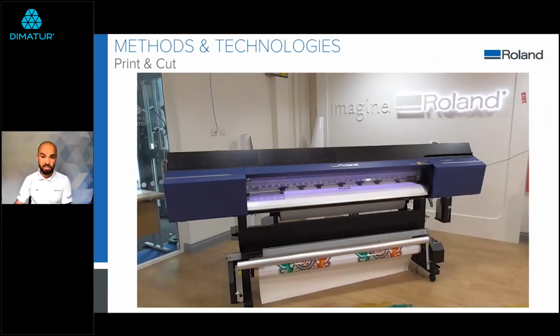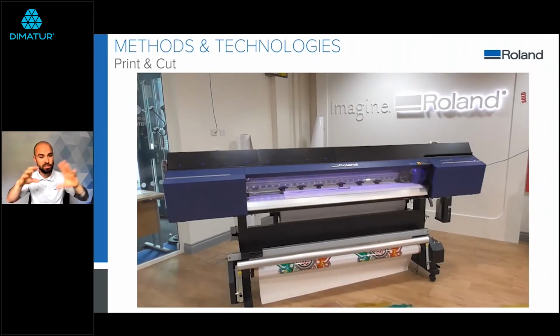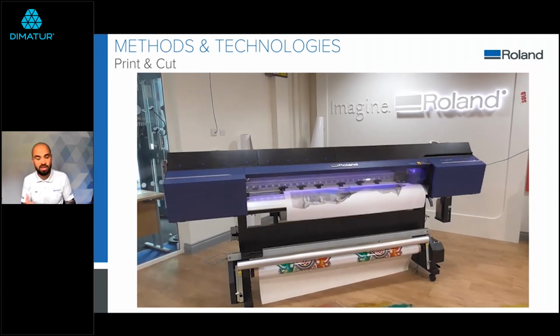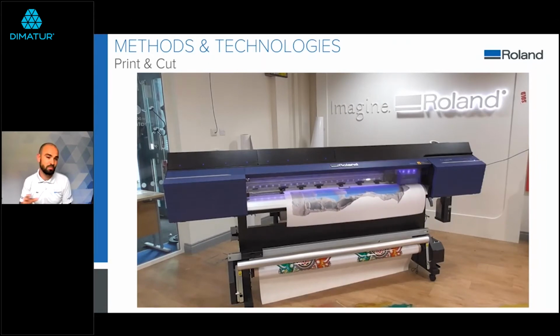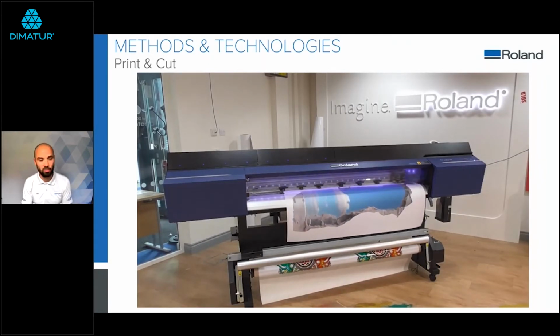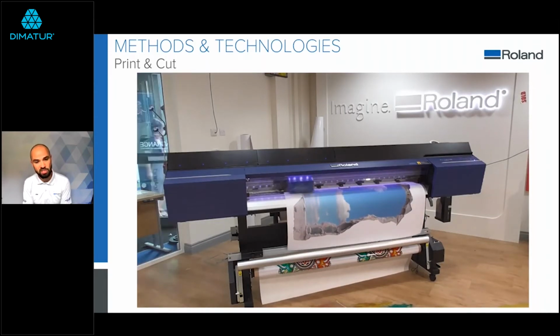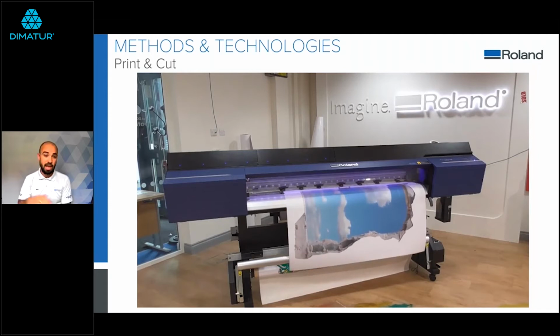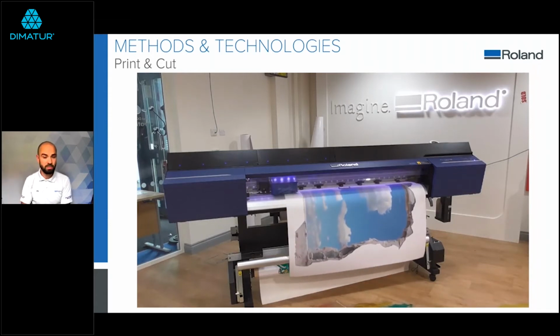So again, what I've done is I've print and cut an application to show you some of the processes. This one's using the VG2, and we were printing a graphic that looks like a hole in the wall, a common sort of application that people like, playing on the idea that you've got a hole in the wall or something bursting out of the wall. As you can see here, it's got some sky sat behind some brickwork which has been printed, and then the printer will print that out, wind it back, and then cut it out.